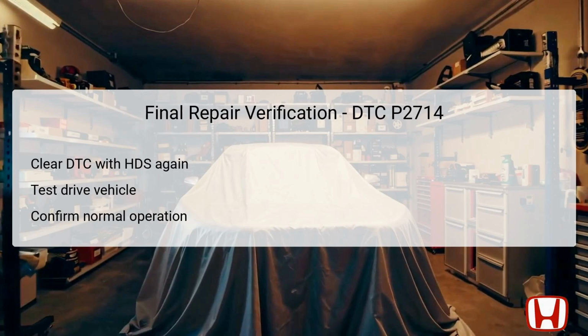After completing repairs related to DTC P2714, it is imperative to conduct a final verification process to ensure that the issue has been successfully resolved. Start by clearing the DTC using the HDS for a fresh diagnostic environment. Next, take the vehicle on a test drive, specifically monitoring the transmission behavior while shifting through various gears.